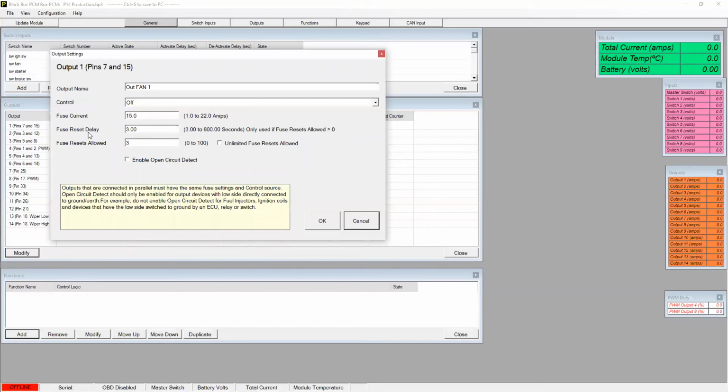So as long as you're within that time frame and it steadies out to about 15 amps, it's really common for electric motors and pumps to see crazy high inrush current. You could see 100 amps for a split second, but having that much inrush isn't going to burn or hurt the wire. The wire's not going to really get hot if the inrush current only hits for a fraction of a second. Otherwise, you'd see it steady out at under 22 amps more than likely.